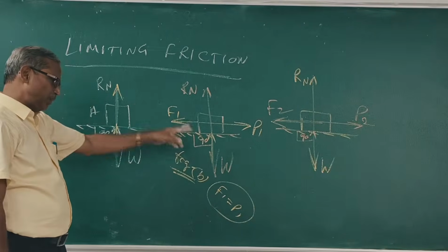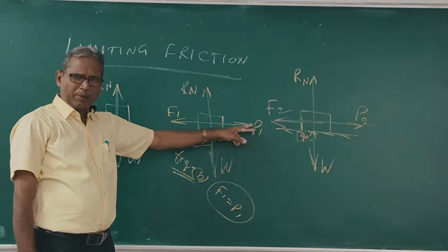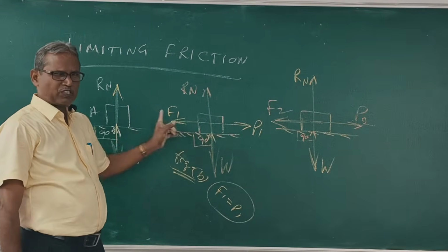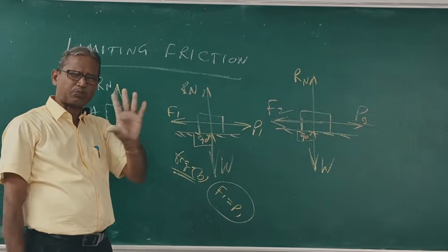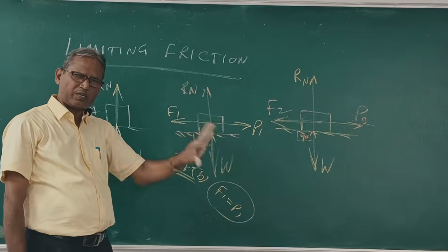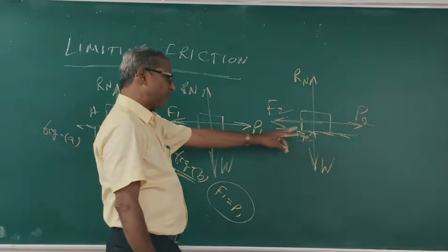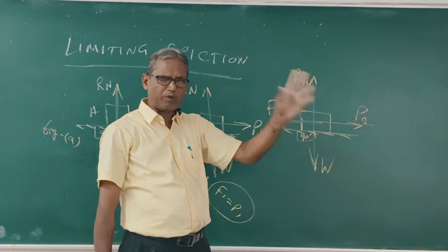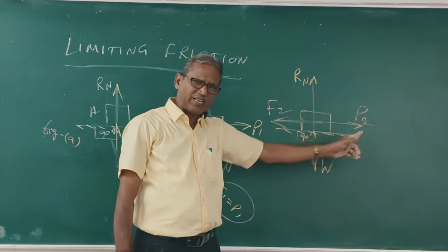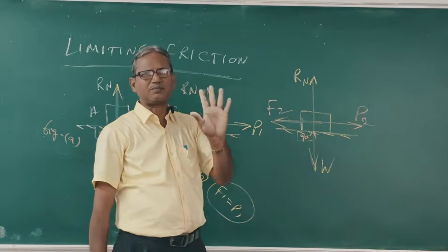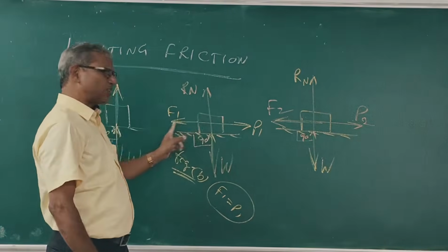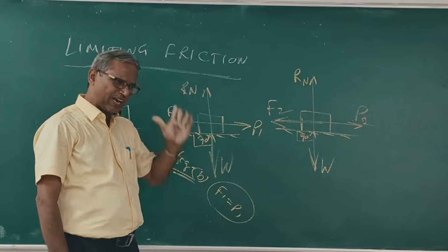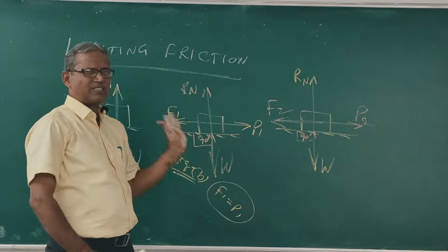In figure B, I apply some force P1, and the frictional force F1 balances P1. The body is in equilibrium. In figure C, I slightly increase P1 to P2. When the applied force increases, the frictional force also increases. The frictional force F2 is more than F1. So a slight increase of applied force slightly increases the frictional force.